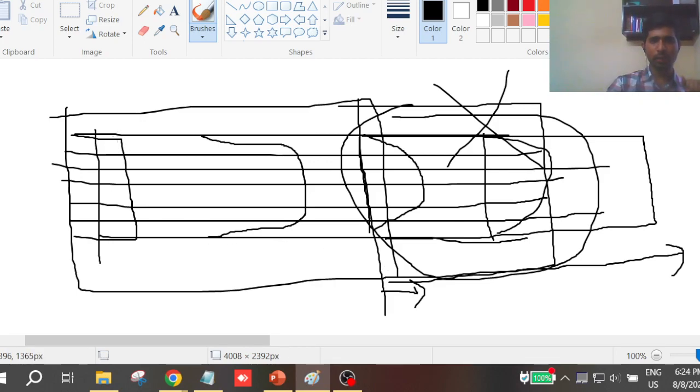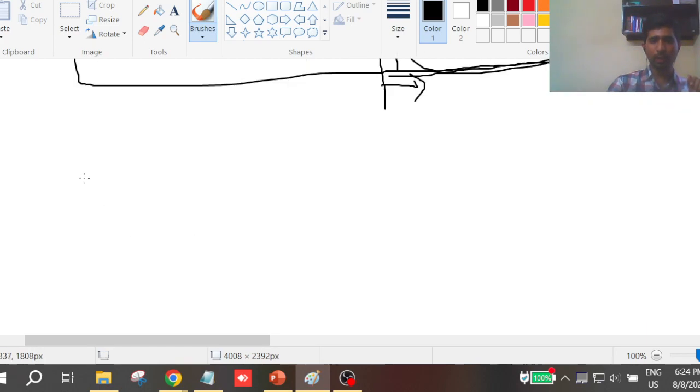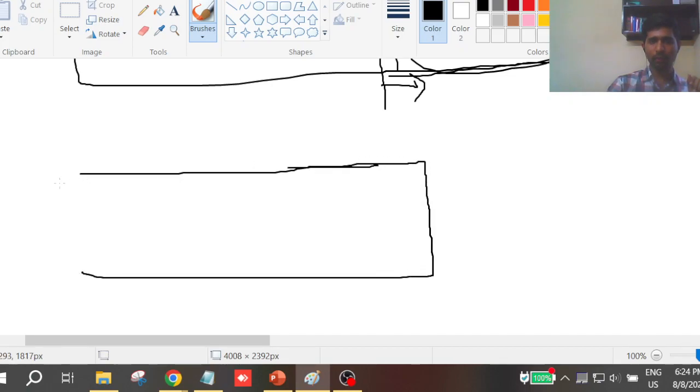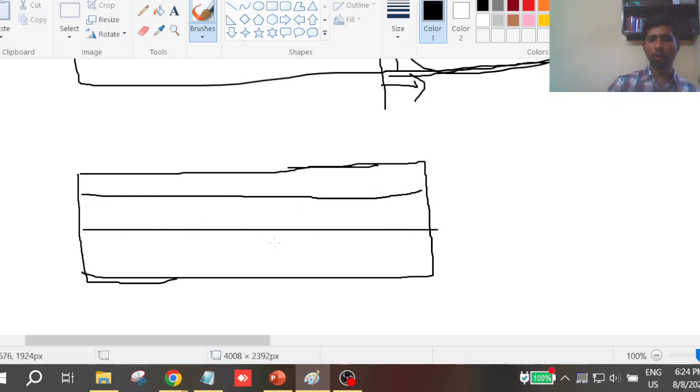As I said, the second step, after taking the domain, is that you have to decide what type of grid to take and the number of grids. First let me touch upon what type of grid to take for this particular problem. This is just a rectangular channel, so the domain itself is a rectangle. Here you can have a very rectangular kind of division of this whole rectangular domain.